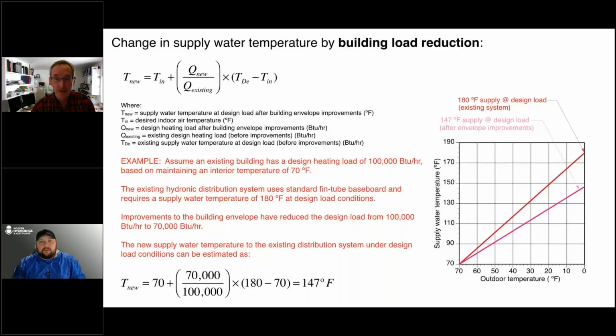There have been some fin tube elements used in what's called valance cooling. You could check out Edwards Engineering in New Jersey, which has had this system out for years. It's basically a fin tube that goes up near the ceiling on the wall, and it has a valance that goes around it that captures the condensate.